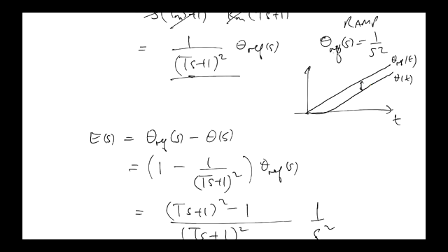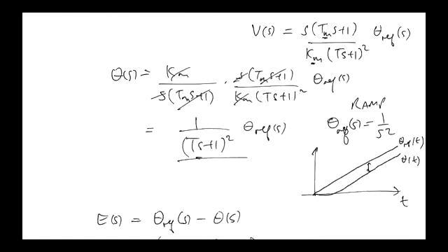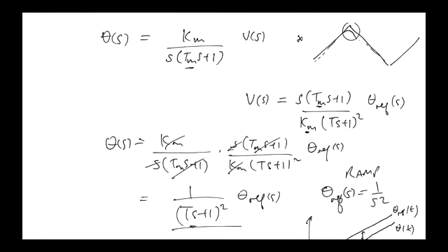So what's wrong with open loop control? Seems to be fantastic. All I have to do is make those extra poles super fast, and I'll get a very small tracking error. Well, the problem is that in order for these things to cancel out, I need to know the parameters of the motor model exactly. Right?